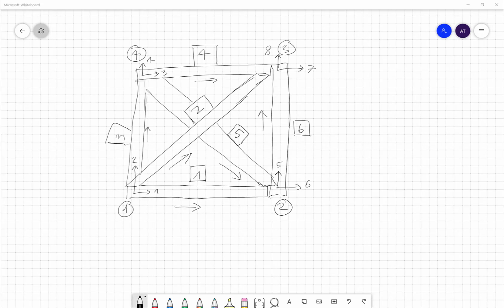Here, displacements 1, 2, 3, and 4 are unconstrained displacements. And these 4 unconstrained displacements, or these 4 degrees of freedom, are code numbered first. Displacements 5, 6, 7 and 8 are constrained and located at the supports, so their values are all equal to 0.